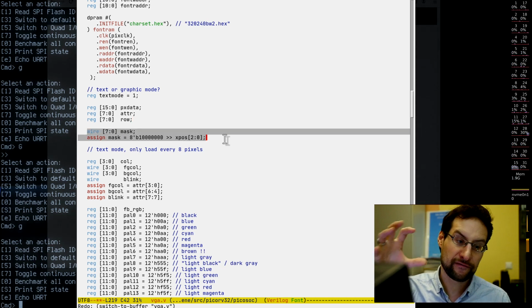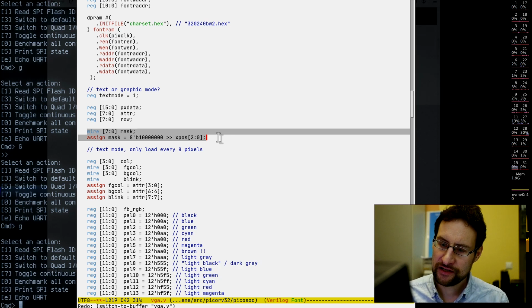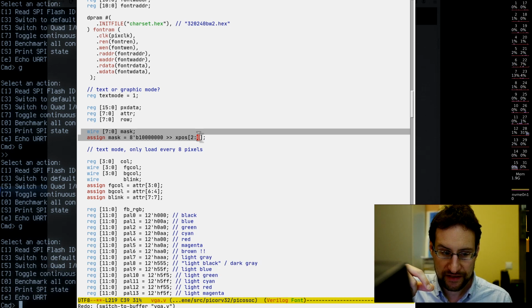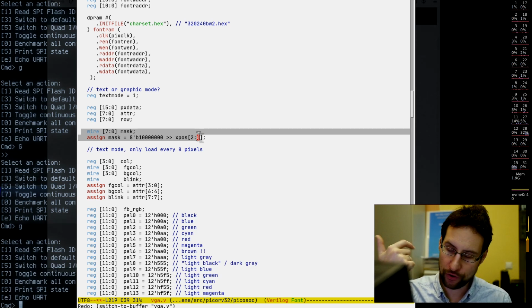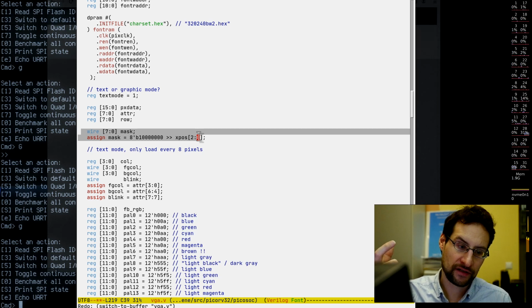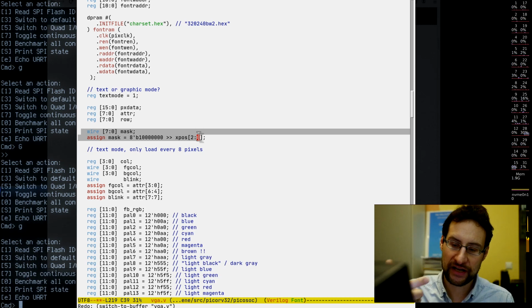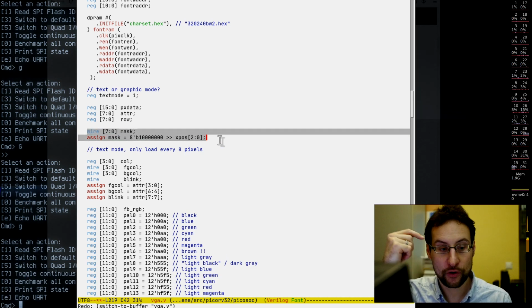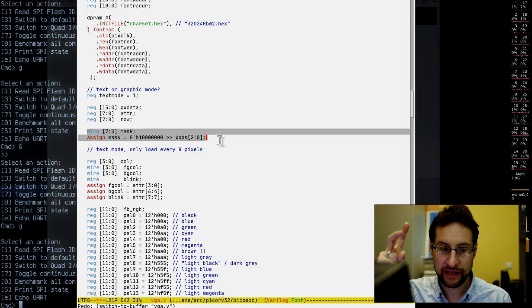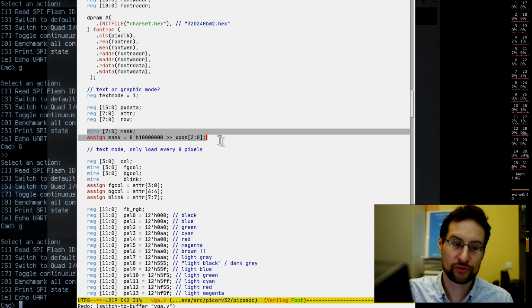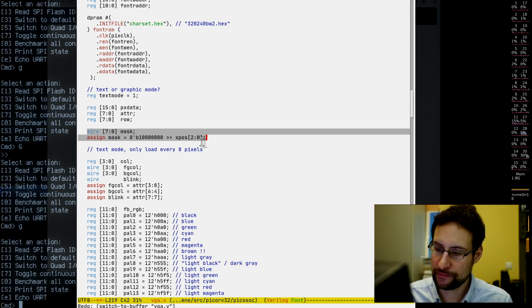Some neat tricks I learned. I heavily combined sequential and combinatorial logic. Earlier I computed those masks in the pixel clock generation. However, I learned that it is much more efficient and faster, because with blocking versus non-blocking assignments, a non-blocking assignment only updates at the end of the cycle. This here is combinatorial logic, always without flip-flops, not buffered, and this logic is always active, as in the 0 and 1 binary input, it's always receiving those. As soon as those register bits toggle, the output follows with a propagation delay of a couple of nanoseconds, which is how long these logic elements need to switch.